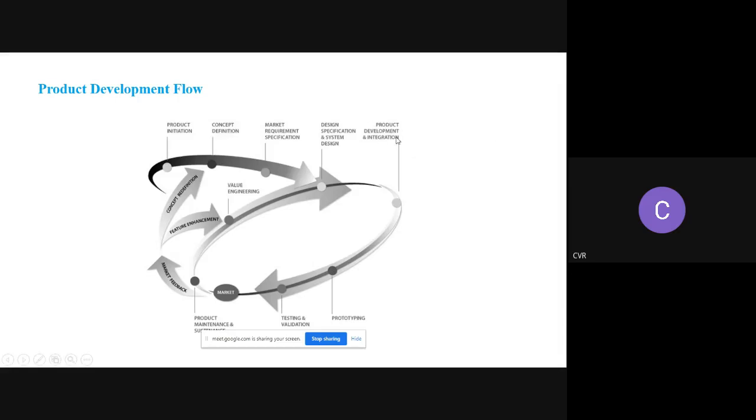The software team typically works on the evaluation board, develops the code, and sees the performance there. For electronics, you have to design the circuit, get the PCB done, and after assembling the components, start the testing. Once that is done, the software will be downloaded there, and you will check the performance. Then you will go for the final testing.